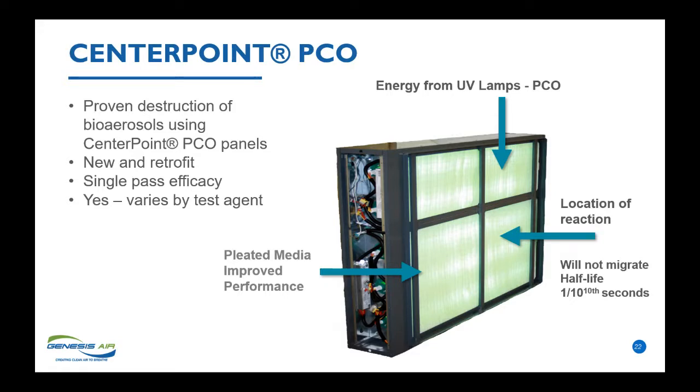We have a pleated media, which means 6-inch pleated media on 1-inch centers, so instead of a 24 by 24 panel, we have a significantly bigger panel when you undo that accordion, which gives us improved single pass performance. And last but not least, we've not spent a lot of time on that, but the location of the reaction is only in the panel.